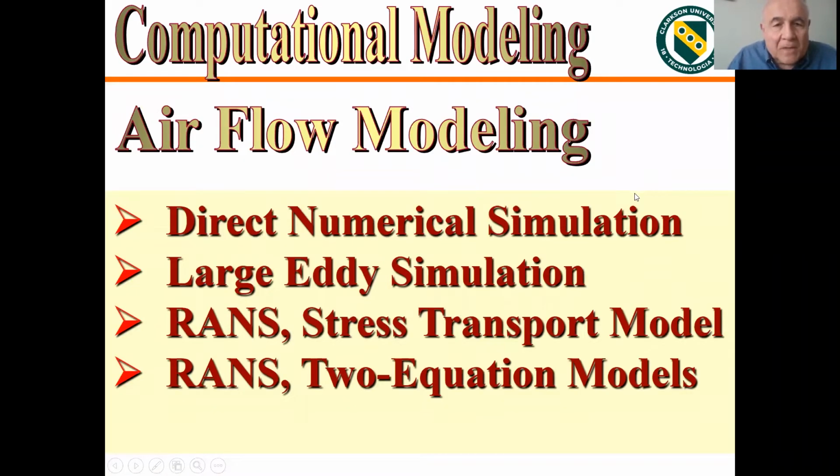Well, basically for modeling airflow, as I'm sure this community is well aware, there are different techniques. DNS, direct numerical simulation, is probably most accurate, but very expensive and also not practical for complex geometries. Large eddy simulation has come along quite a bit. Now it can be applied, still is extensive calculation, but becoming more practical as computer power increases. A RANS model with various turbulence models still seems to be the practical approach to simulate airflow and aerosol transport.